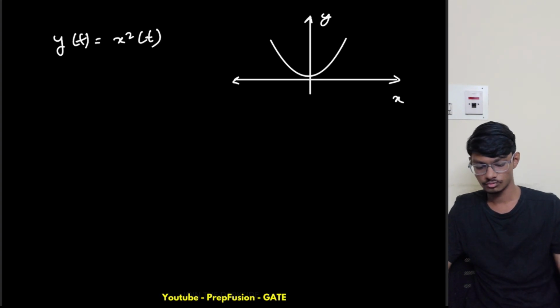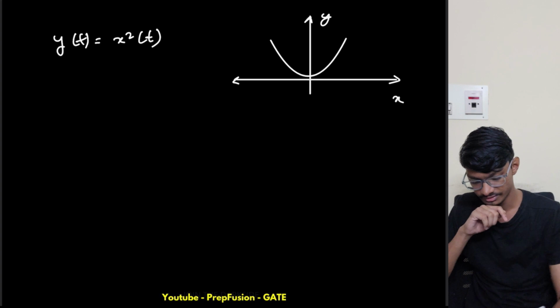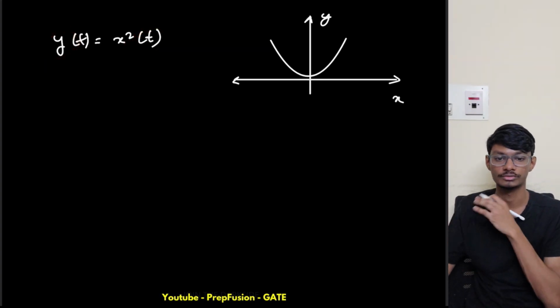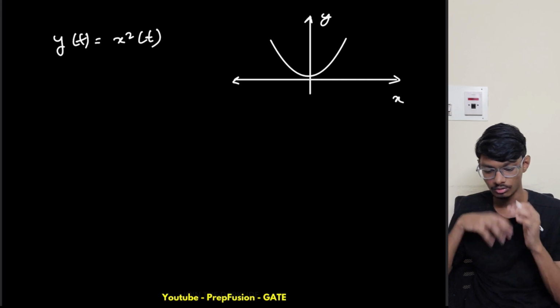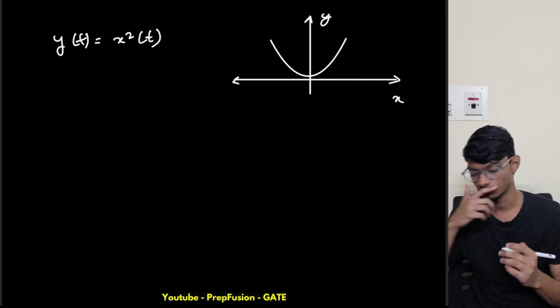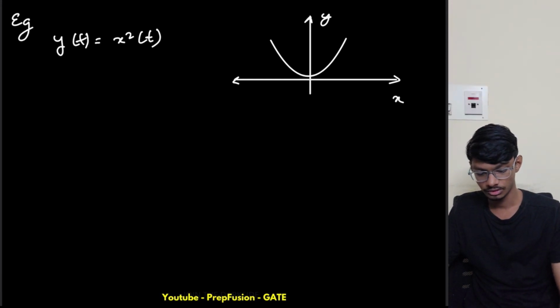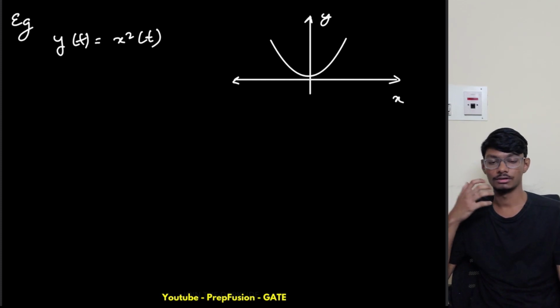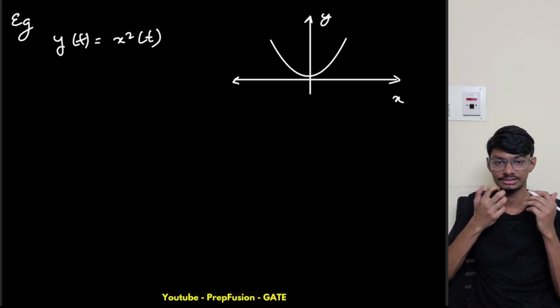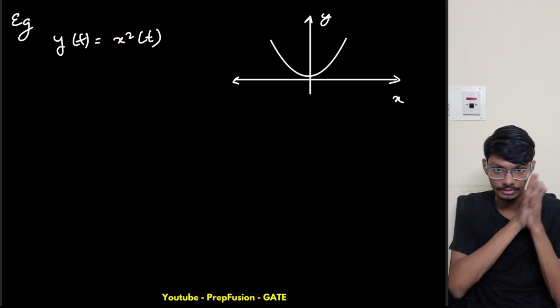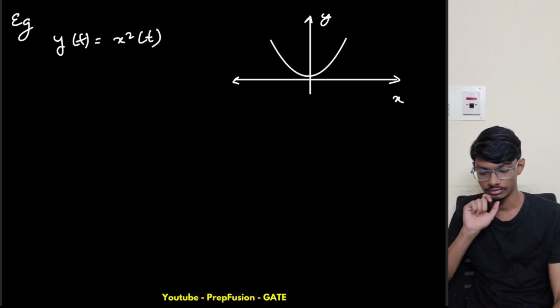What I will do is shift this x of t by t naught, then this output should also be shifted like this only. So how do we prove time invariancy? This is an example. I will simply find the response of this input signal after shifting the whole bracket term by t naught.